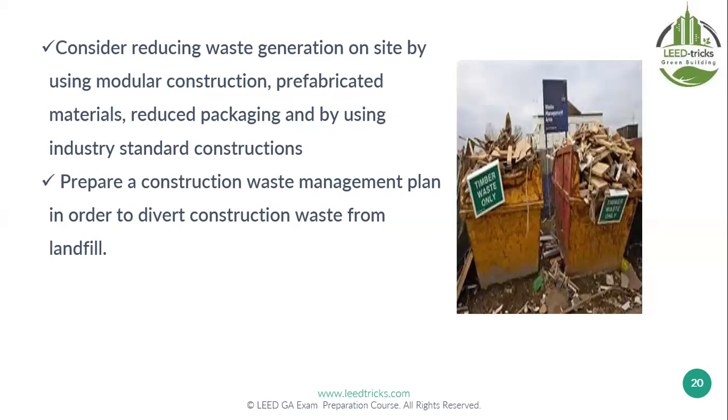Using slip form or some kind of formworks will save a lot of waste, like what you see here in the picture. This way we call waste reduction strategies on site during design and construction. In this credit, you need to prepare a construction waste management plan. If you are working as contractor, you will prepare this plan, not the design consultant.